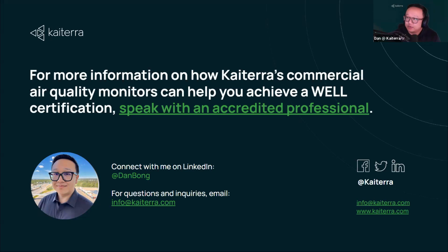Great. We have a couple more coming in here from David. What frequency should sensor replacement take place? Great question. So for WELL certification, you do have to have these sensors recalibrated every 12 months in order to resubmit for WELL recertification. So for WELL projects, you do have to replace them every 12 months, because the recalibration process for our sensors is the physical replacement of a newly calibrated sensor going into the device. So for WELL certification, you're looking at 12 months.